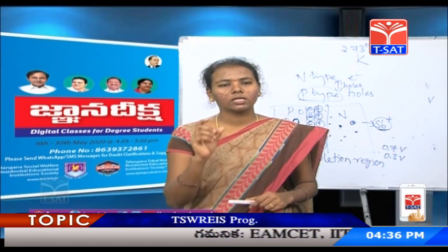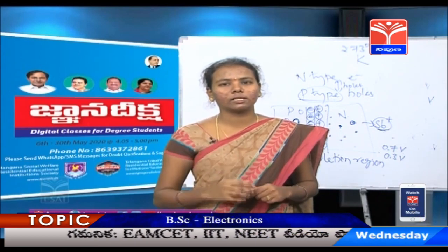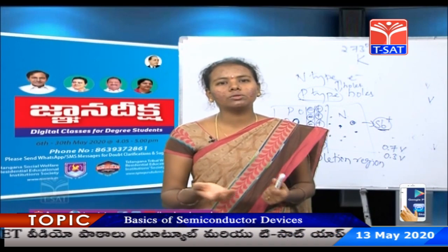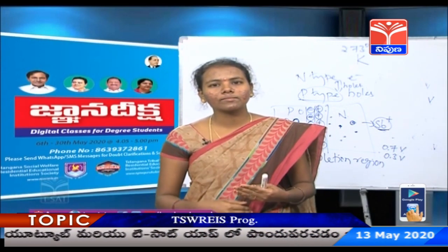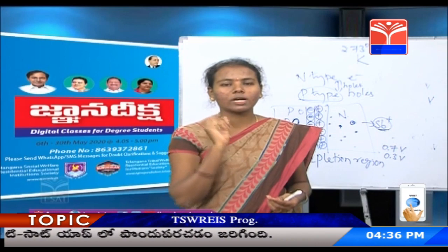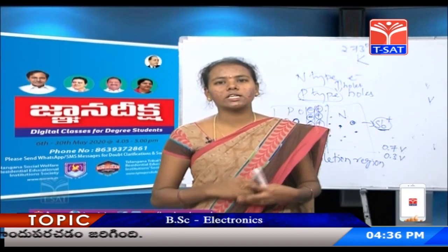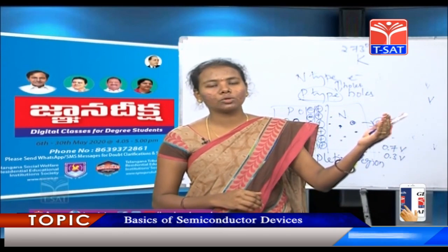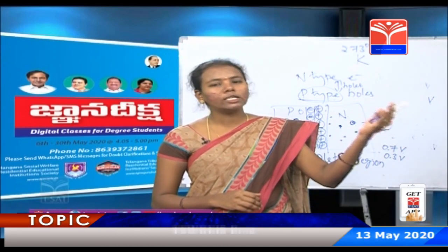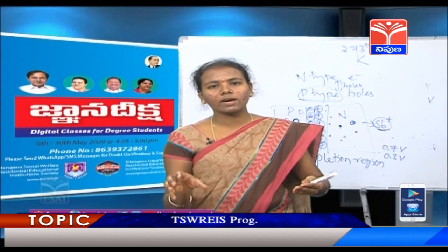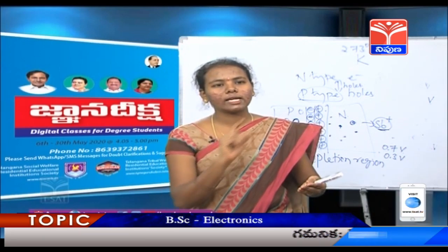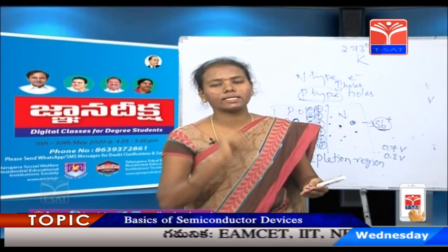If you see, the bulb rating will be 6 volts or something. The 220 volts will not be used. So how is the 220 volts decreased? We are using a step down transformer there. A step down transformer converts the incoming 220 volts of alternating current into the rating of whatever the device is using. If it is 6 volts, then it will convert into 6 volts of AC.